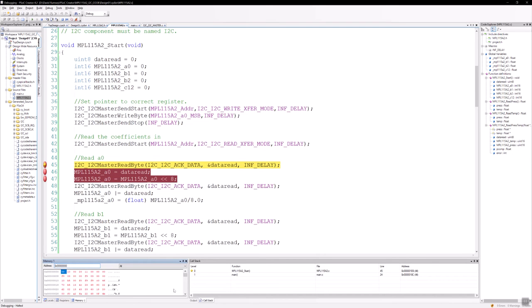So this is actually the memory that's physically on the device. You can see the first bits here are the actual program that we've written, all the machine code and everything, and we don't know what all of that means. We could look it up, but if you go through, this is what's stored in the actual chip as far as our program. And then of course we can look at the registers. Red means the value has changed since the last line of code.